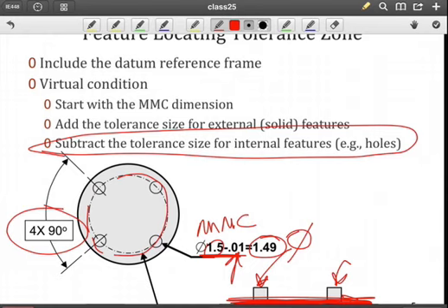So we have 4 pins that correspond to the 4-hole pattern, and as you can see, the outer circumference, which corresponds to B, has no role in this location of the tolerance zones. And so this 4-hole pattern can vary. Again, it's a tighter tolerance than we saw for the pattern locating tolerance zone, but we're more concerned about the features related to each other.